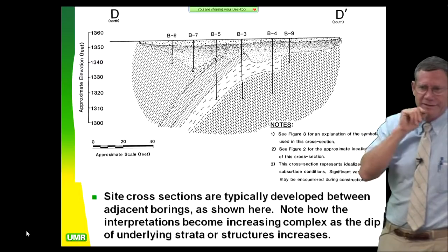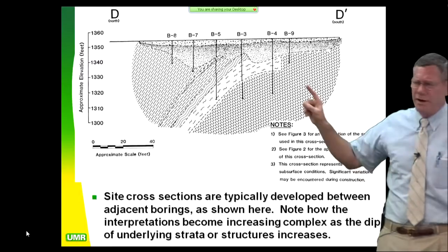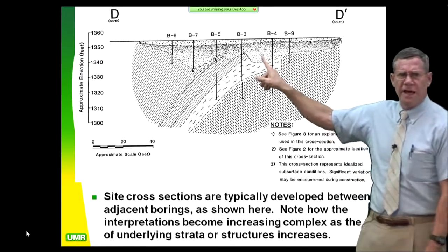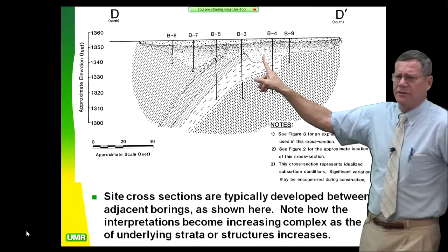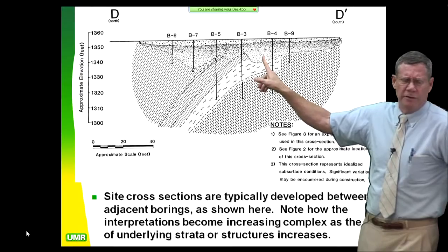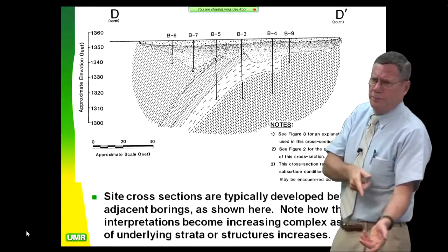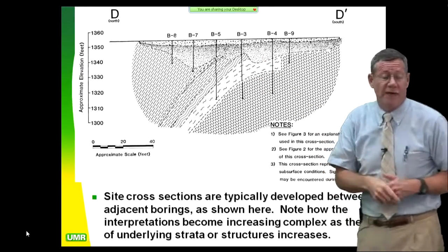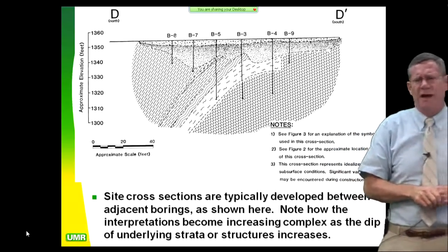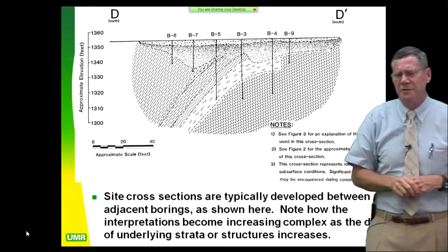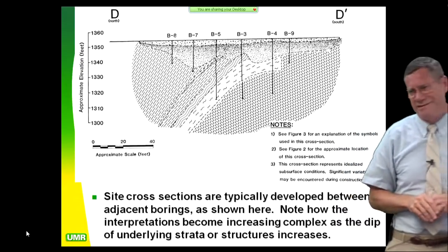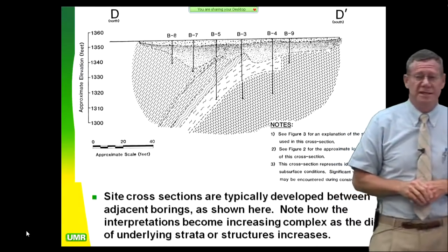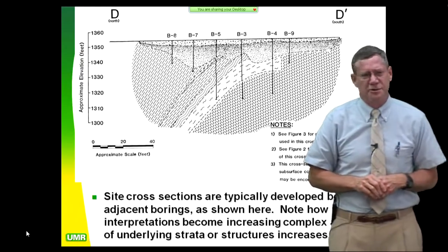One storm. Wow. Very, very angular material. The phi angle of this material, 45 degrees. 45 degrees won't help you if you have concentrated flow pouring on it for hour after hour after hour. That storm duration, by the way, was 35.5 hours. That's a long duration storm. Average storm duration, coastal California, 90 minutes, hour and a half. So to go 36 hours, that's a pretty unusual event.